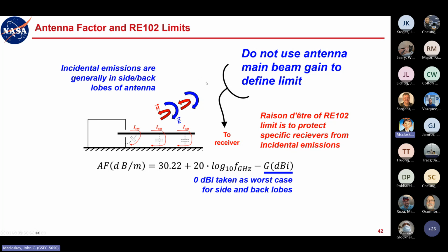They can say that, okay, we know we're at least minus 10 dBi of gain for however the antenna is going to point during the mission. If you know that, you can say unequivocally that it's going to be minus 10 or what have you, then you can use that. But as a starting point, I generally use 0 dBi as a worst case.